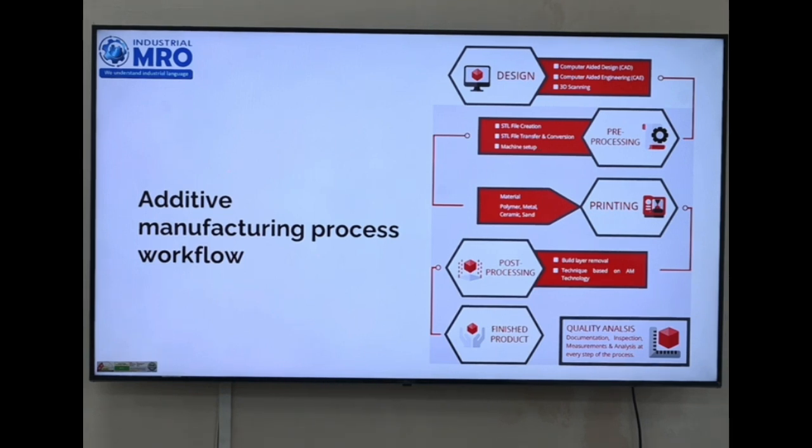slicer, and then the slicer slices the part, and we can give the settings like what material I need and what the temperature is, let's say PLA. PLA temperature is around 190 to 220 degrees Celsius. ABS is much higher, 250 to around 280 degrees Celsius. So based upon the material, you will define the temperatures there. You will define other requirements, like if I need a brim, a raft, overdrafts and all those kinds of things, we can define in the slicer, and we can give the command in the slicer and then get the 3D printed part created.